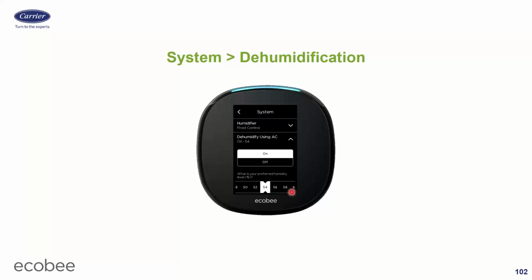It's going to run that until either A, I hit the heating set point if I'm in the auto mode, or B, I go more than 3 degrees below the cooling set point because that's what I had selected, 3 degrees max overcool. So in my case, 71 degrees because I had a 74 degree cooling set point. Or C, it'll shut off when I hit the 54%. One of those 3 things is when it'll shut off. Or you rip the stat off the wall. That'll do it.